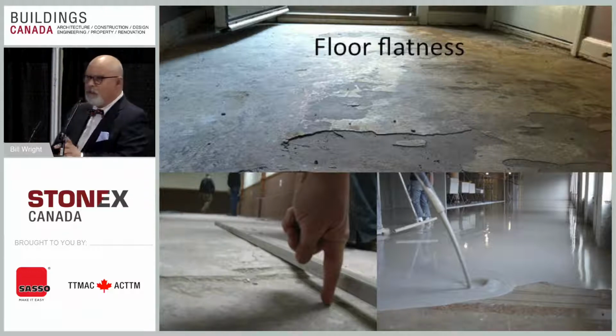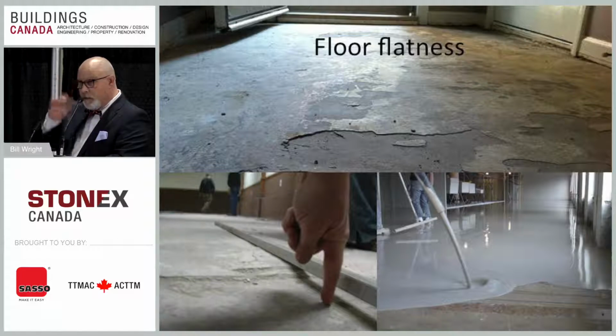Retrofit is a little more difficult because we're working with existing conditions. There are self-levelers out there. They can go from nothing, a zero feather finish type of profile, up to usually about 12 mil over existing tile and old adhesives. Many things don't need to be ripped up. You can go right over top of them if they're good and solid.